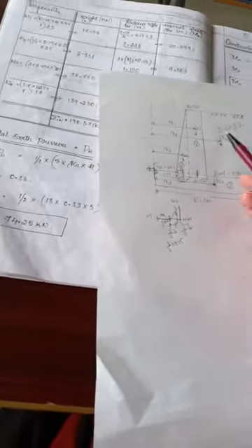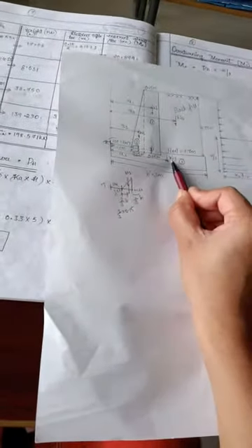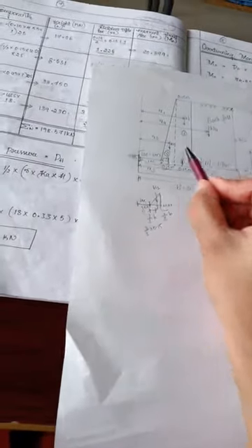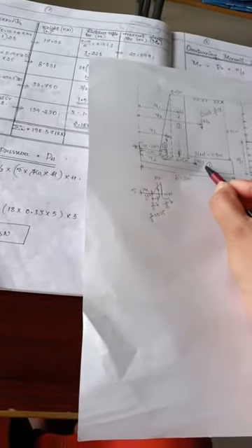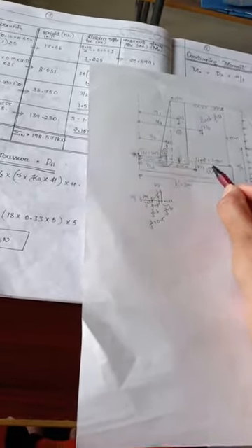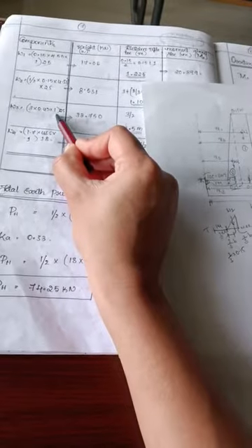After that, now we are going to find the W3 value. Where should this W3 value act? In this part. This one is the W3 value. Here once again we get a rectangular portion. To find W3, which formula do we use? Length into breadth into height. Length means every 1 meter, so we consider the length value as 1.